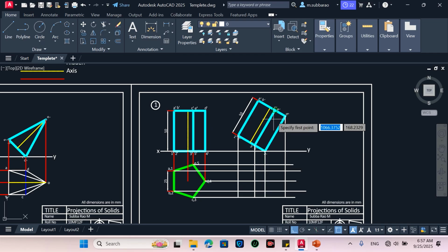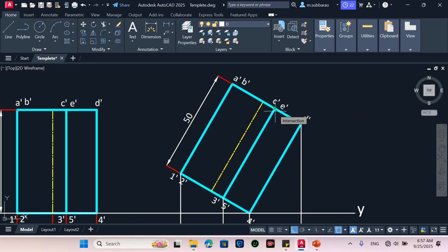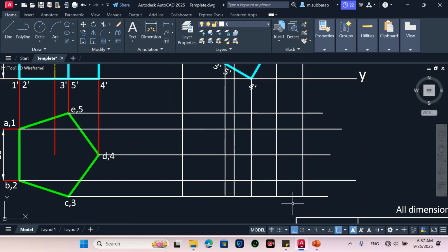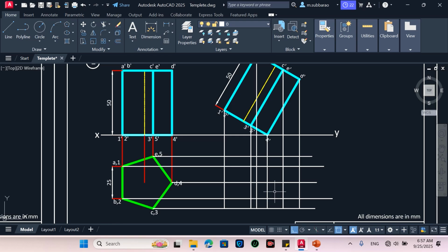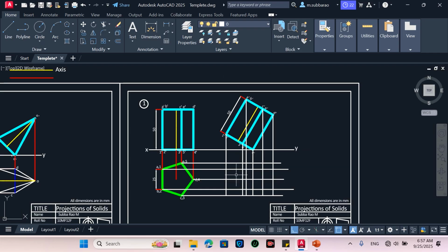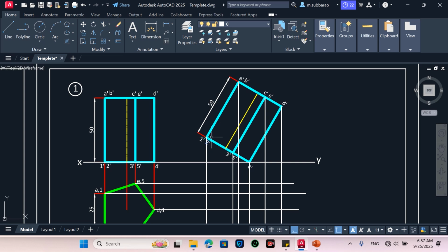Now you see how many projection lines are coming, all are coinciding with each other, but still I need to draw the projections, and I should not get confused. Usually I get confused, because there are many notations, 1 2 3 4 5, which are the bottom base, but which point is the bottom base, where the bottom base is actually appearing. So now if you see from the leftmost corner to the rightmost corner, I already told you whatever is above this line will be visible. So that means the total top base will be visible.